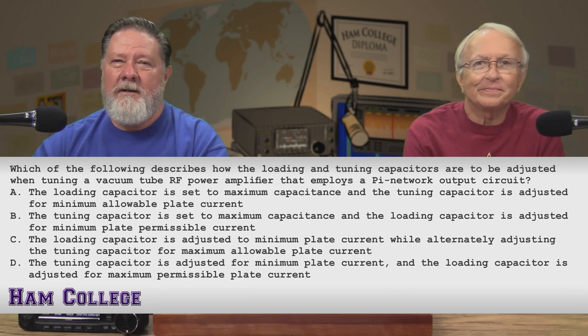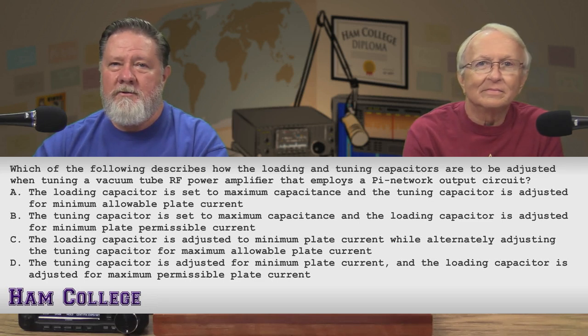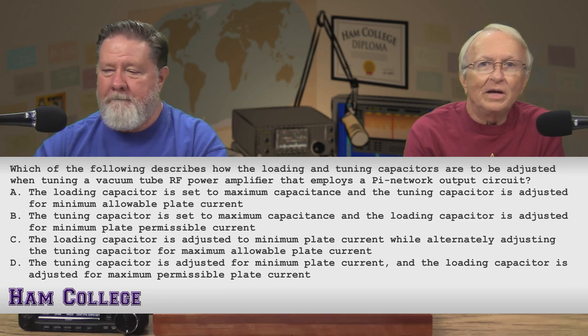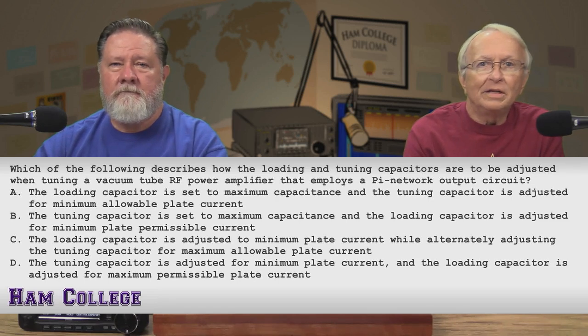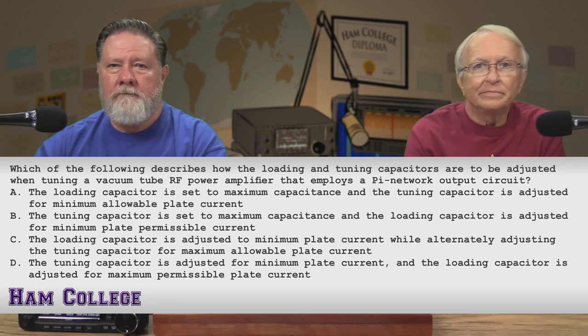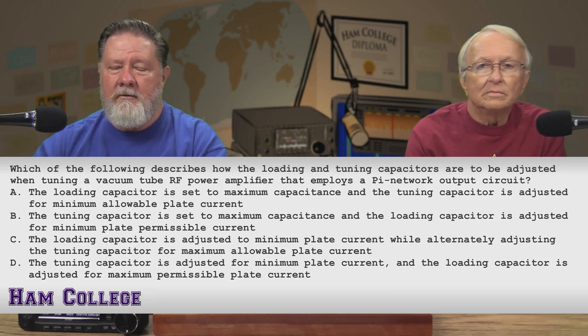B, the tuning capacitor is set to maximum capacitance and the loading capacitor is adjusted for minimum permissible plate current. C, the loading capacitor is adjusted to minimum plate current while alternately adjusting the tuning capacitor for maximum allowable plate current. D, the tuning capacitor is adjusted for minimum plate current and the loading capacitor is adjusted for maximum permissible plate current.